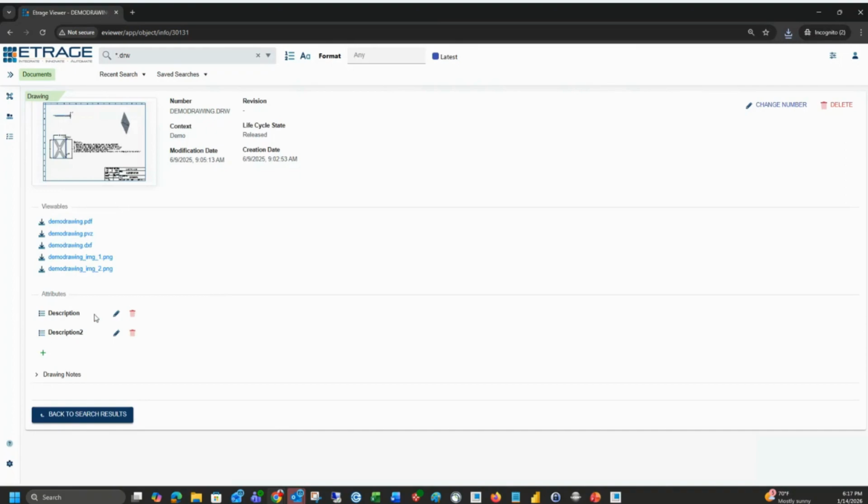And on this page as well, I can also create or capture the custom attributes that are coming from my source data, whether it's from the local or from the Windchill system. I can also capture those additional attributes such as material, description, and maybe supplier for a material in this information window here.